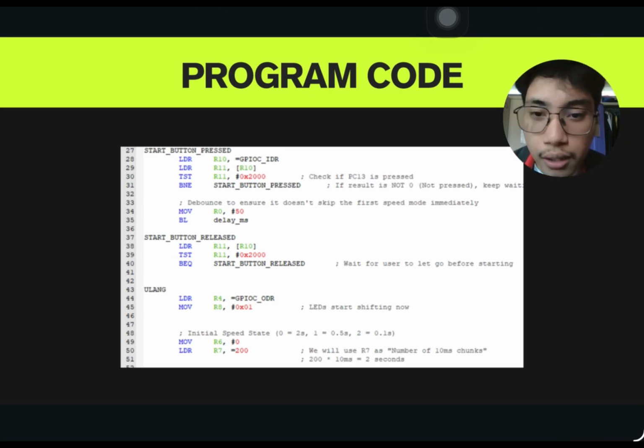Okay, so for the second part, there are mainly two parts, which are the start button press and the start button release. This ensures that when the button is pressed and released, then and only then the LED will start shifting. So holding the start button, or the push button, will not execute the command to light up the LED and start the shifting LED.